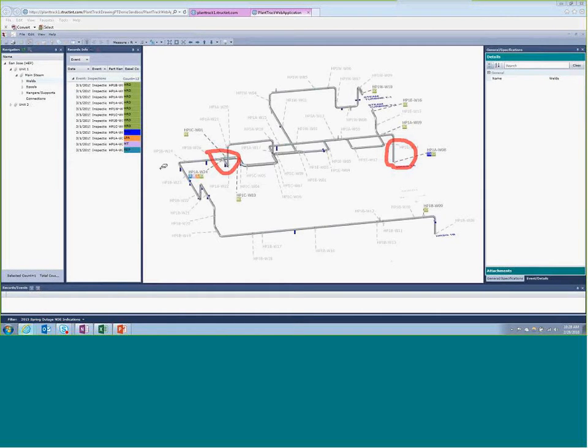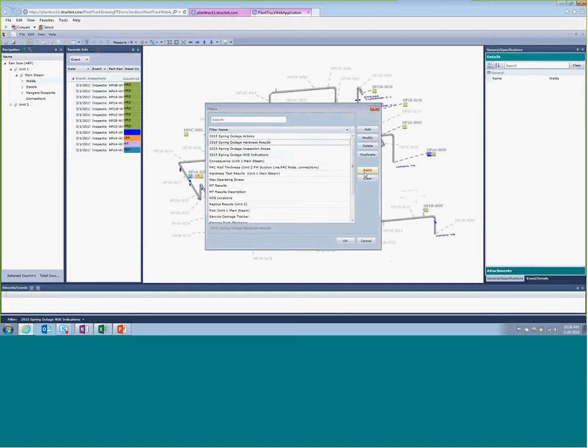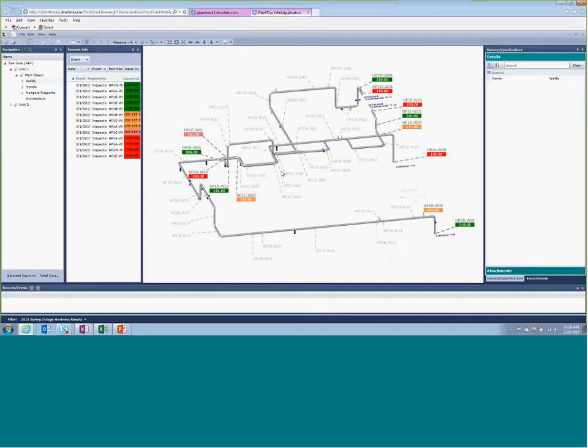So what's neat is that if we say, okay, we know we have some hardness flags that popped up, okay, what were these values, and it shows the general range. So I can go through here and say, okay, the hardness values that we got, SI has our standard range, what we consider hardness to be acceptable and what we consider hardness to be unacceptable, so these filters were built accordingly. Again, if you have your own internal procedure, that can be customized to that. So I think this is a really powerful tool, especially as you build on it, looking at all your welds, doing the hardness for each weld, especially with 300 welds. This can give you a good picture of where maybe you had some issues with post-weld heat treatment, or just overall fabrication issues from the supplier.